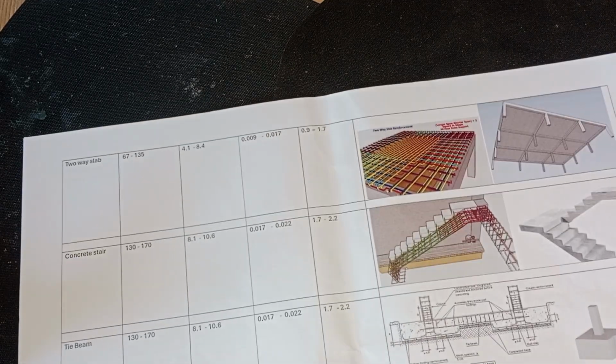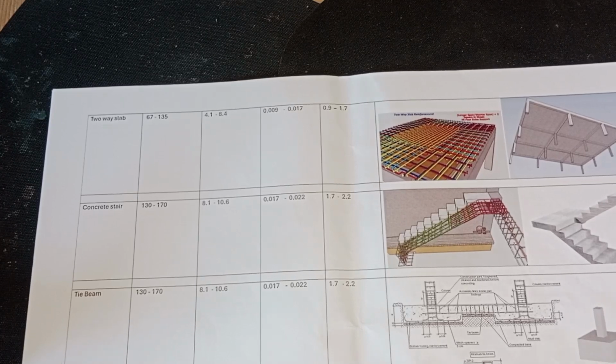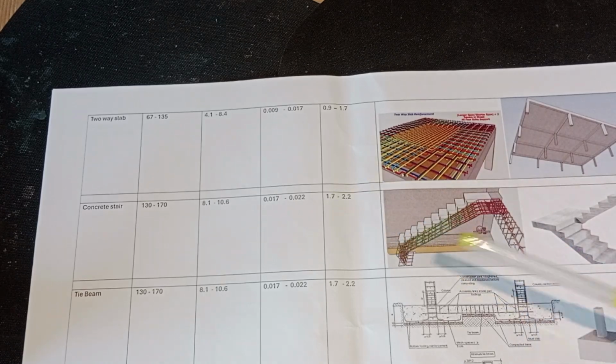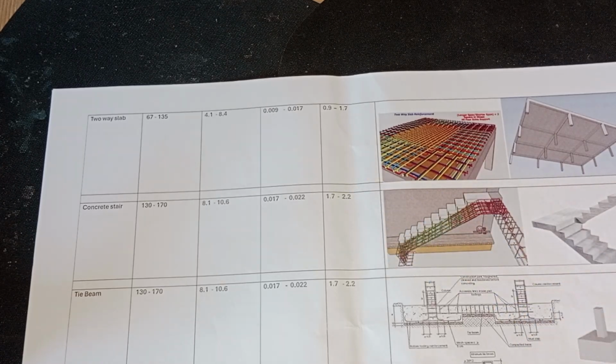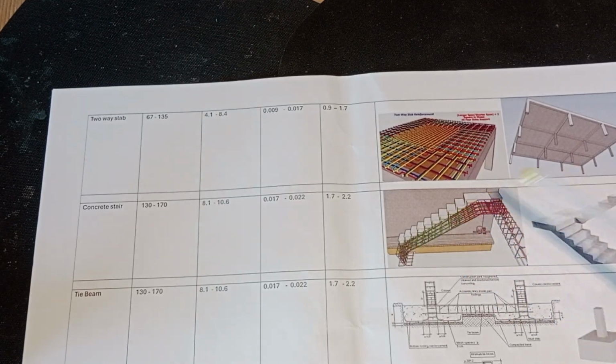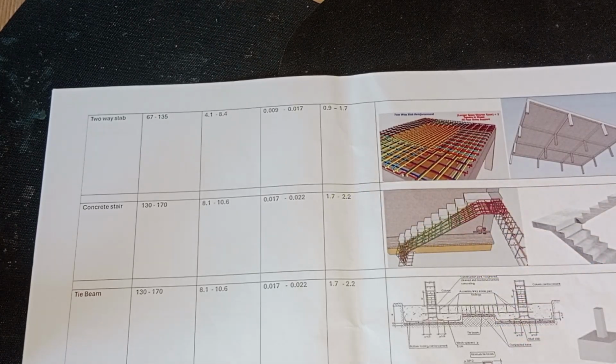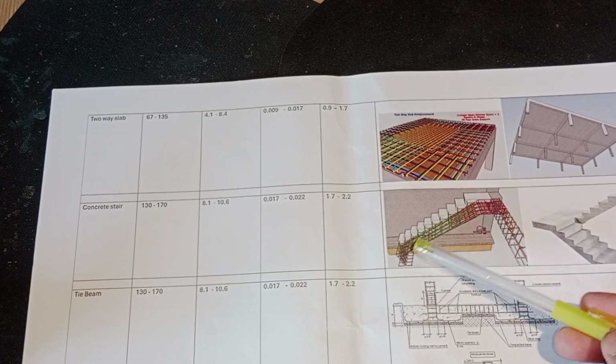Concrete stair is the next. If you have about 130 to 170 kilogram of reinforcement in unit volume of concrete, that is ideal, and the percentage is about 1.7 to 2.2. You see that for such a small section or such a small structure, we have congestion of reinforcement. That's why it's going above 2.2, and we say it is mainly for the connections and the